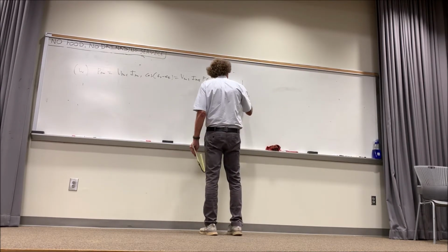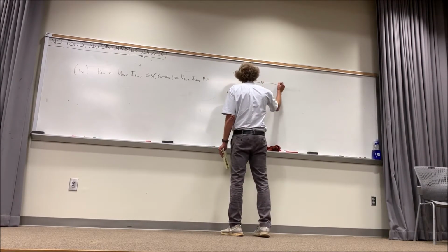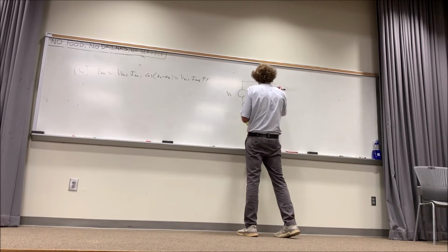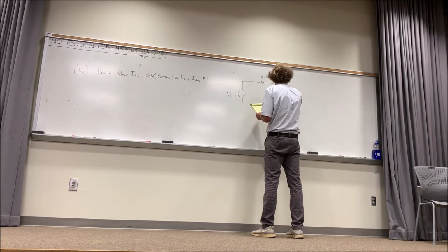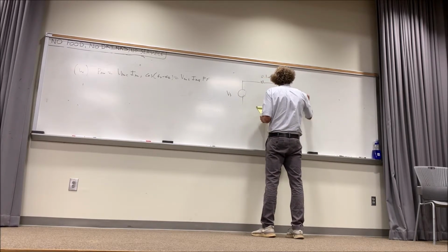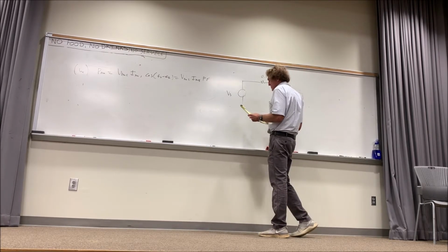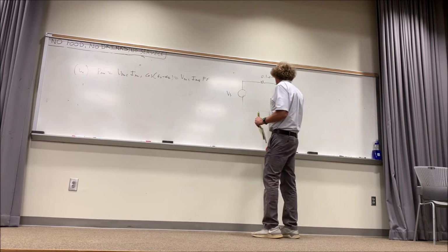So if we have a source voltage Vs here, and we have some resistance, this may be a transmission line a mile long, and it's going to have a certain resistance. Say this is 0.1 ohms. Then down here, the power company, by regulating, is going to have a voltage. One of the typical voltages that they deal with is 480 volts.